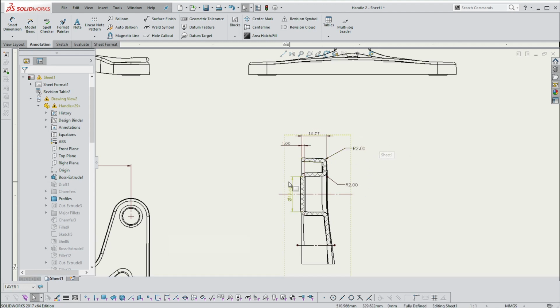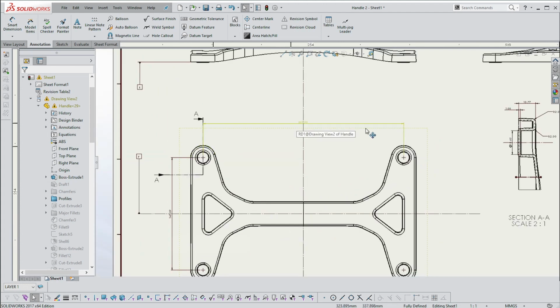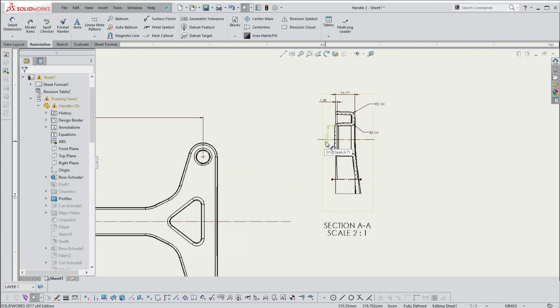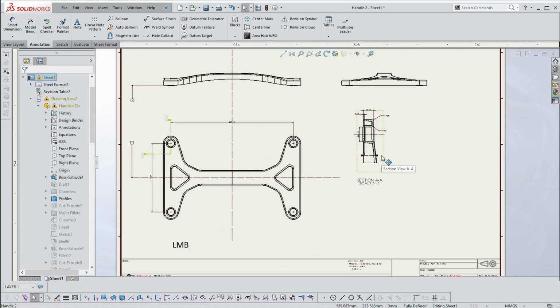And I'm looking only that you understand the difference between position dimensions, which you must have first, and size dimensions, which you can then place in later. So these are all size dimensions. Every one of those are size dimensions. All right, so that covers that.